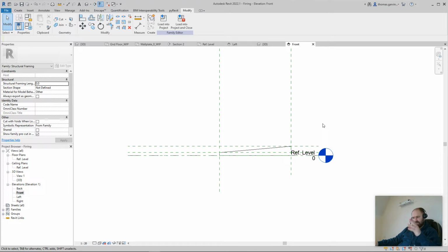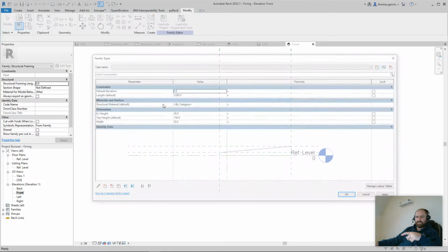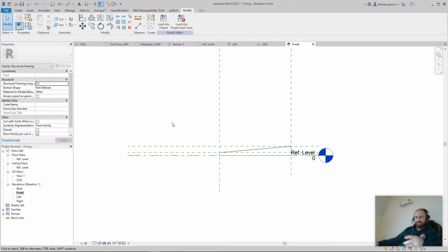But after I place it and after we fiddle with the roof and do all that stuff, we're going to come back and make it a bit more interesting and parametric, right? There's a few interesting exercises in it. We're going to make it where you can control it either manually by setting the height in here. Where do we put it? Sorry, it's in the instance parameters. So the height, the top height, we can change it manually there, or we'd have an option to set it by the gradient ratio, so 1:40, let's say, or by a pitch, so an angled dimension. So we can have all three in, and you can check the box which one you want to use. So that's what we're going to do, okay? But if this serves your purpose, then that's fine.